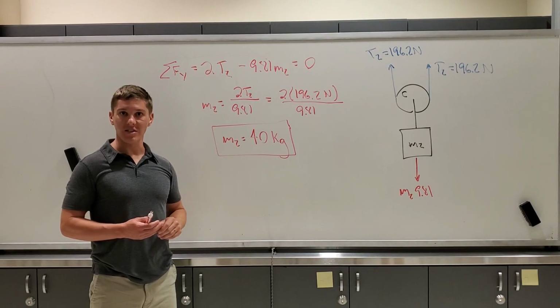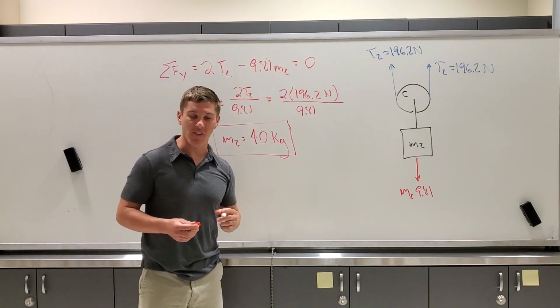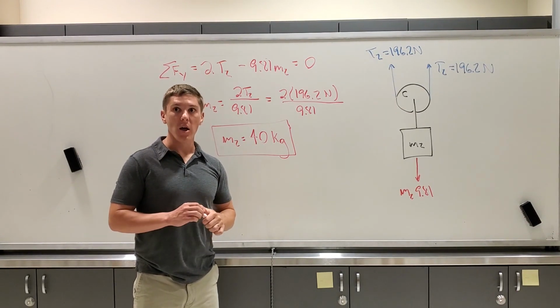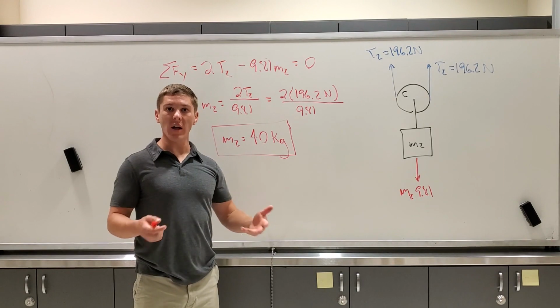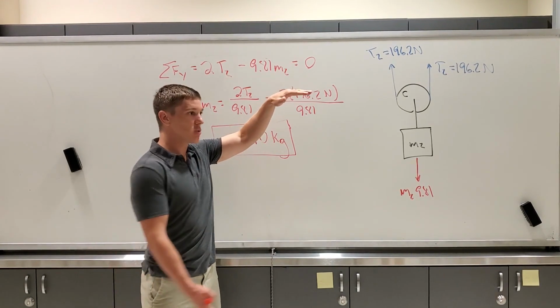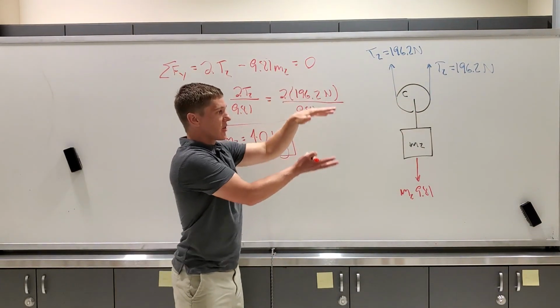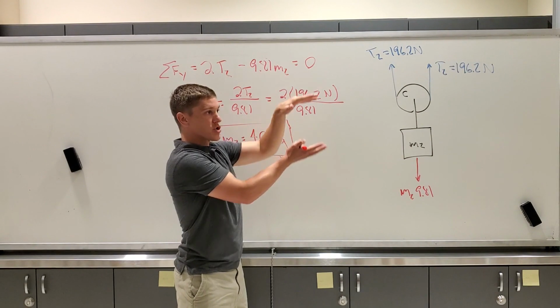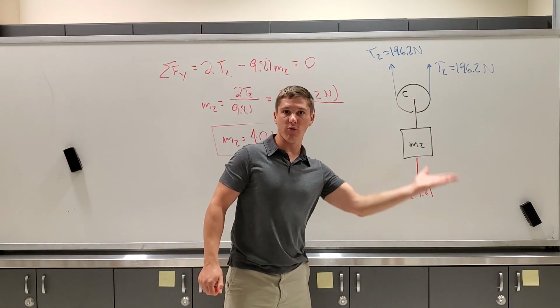That also means, because we can't just amplify force with absolutely no downside, no negative consequence, that the consequence is that if I have a 10 kilogram weight that I'm trying to use to lift a 40 kilogram weight, the distance that 10 kilogram weight will travel will be 4 times further in order to lift that 40 kilogram mass.